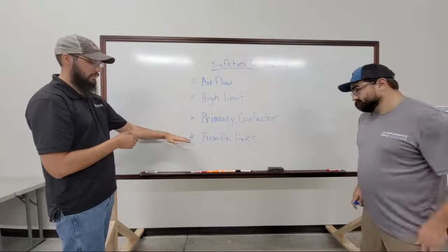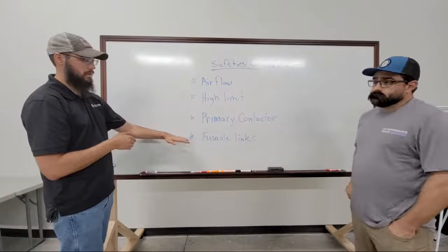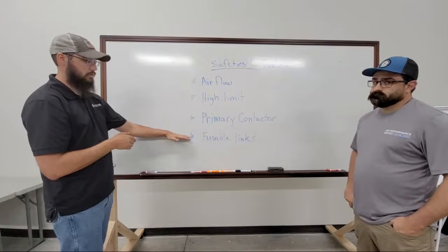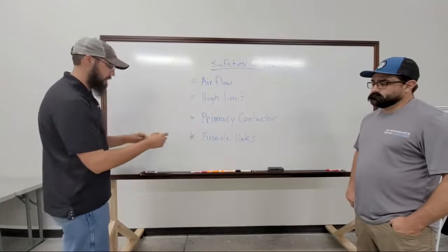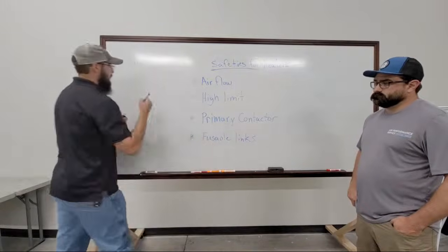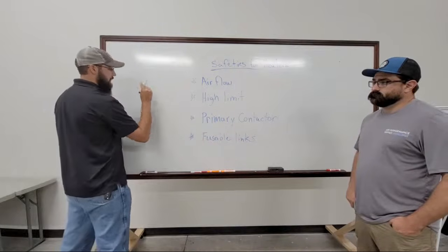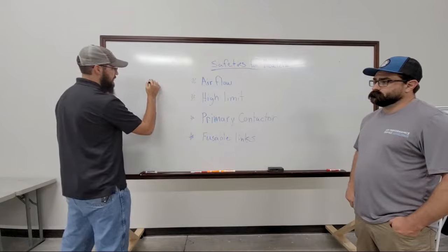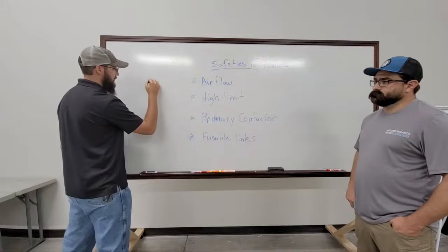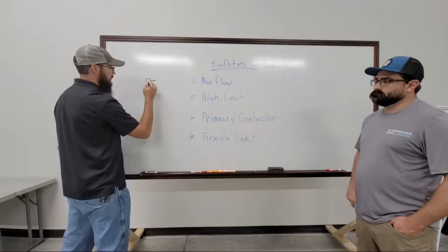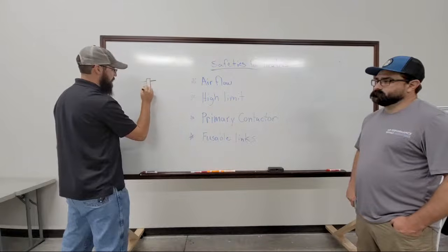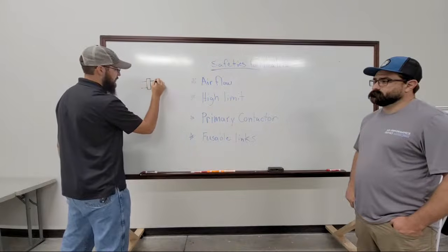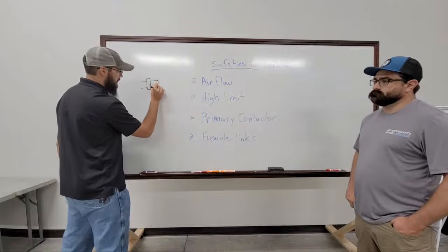Fusible link is always going to be a load bearing control, because it'll be inside of the airstream, but you'll see a little ceramic disc sticking out, and it'll have two prongs on it, and it's literally a fuse.